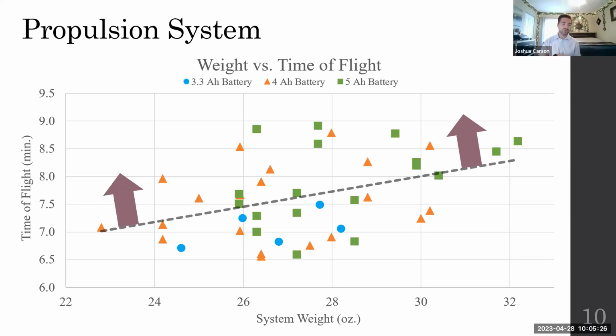Yes, we used a big Excel worksheet to calculate the time of flight based on the battery and the input power and the amount of amps that the individual motors would be pulling from the battery. And so the same motor could use like a 4,000 milliamp-hour battery or a larger, like 5,000 milliamp-hour battery, just pulling power at different rates.